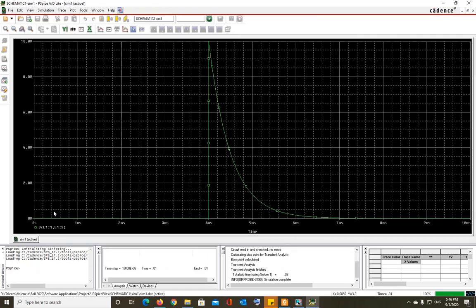and you're going to see that it was 0, and then at 4 the voltage in the inductor jumped to 10 volt. That is, all the voltage of the source voltage appeared across the inductor, and that's one of the characteristics of an inductor. Again, you're going to discuss that theoretically. I'm not discussing it right now. And then it starts going down, because eventually the inductor is going to become a short circuit when it is fully charged.